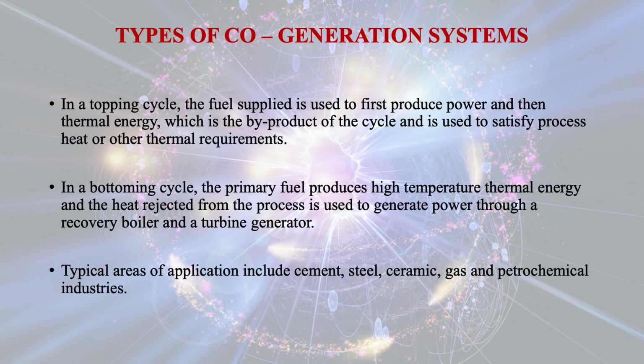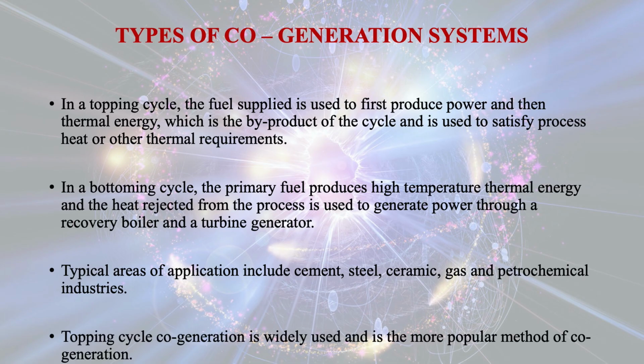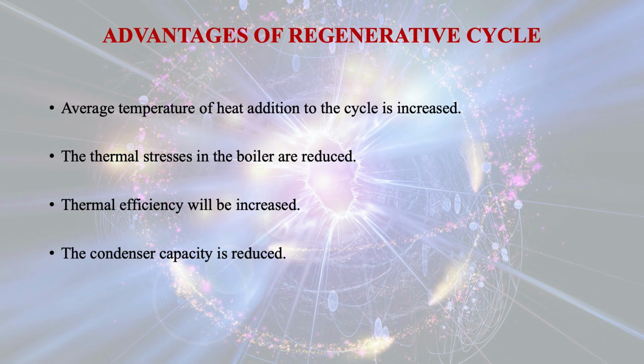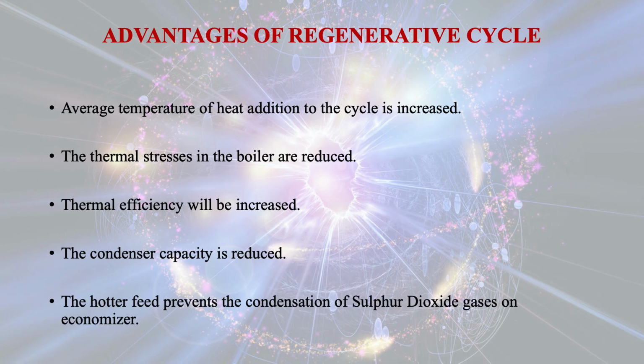There are some advantages of regenerative cycle. Average temperature of heat addition to the cycle is increased. The thermal stress in the boiler is reduced. The thermal efficiency will be increased. The condenser capacity is reduced. The hotter feed prevents the condensation of sulfur dioxide gases on the economizer.